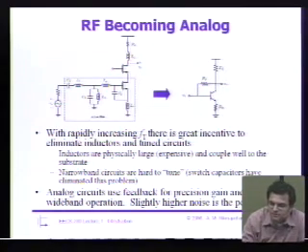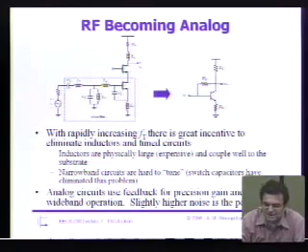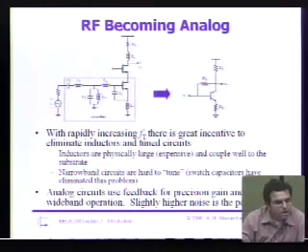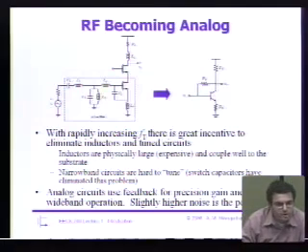Why not just build this amplifier and make it work at FT? Well, what would happen if you try to do that? Stability? Yeah, stability, right? It's so easy. Right when you build any kind of feedback network, there are non-dominant poles, and those non-dominant poles are going to determine the closed loop stability. Those non-dominant poles are all going to be on the order of FT, let's say. So clearly you can't build a circuit that operates all the way out there because it's going to be unstable, okay?